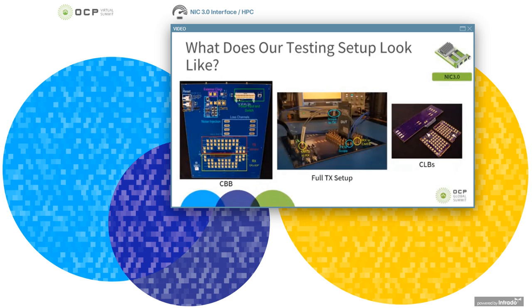Not pictured is our receiver setup, which again is very similar to a PCIe receiver setup. The compliance load board is first used to calibrate the worst case stressed eye signal that the NIC must pass data through at. We use an Anritsu MP1900 as both a waveform generator and error detector, with the NIC and compliance baseboard in between. Once the eye is calibrated, the PCIe signal is sent from the MP1900 to the card, and then the card transmits back again into the error detector.